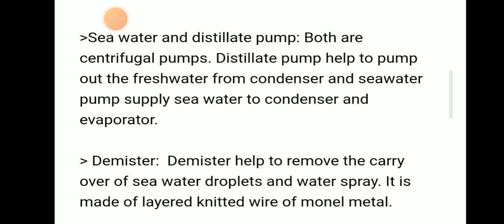Then seawater and distillate pump. Both are centrifugal type pumps. The distillate pump helps to pump out fresh water from the condenser, and the seawater pump supplies seawater to the condenser and evaporator.